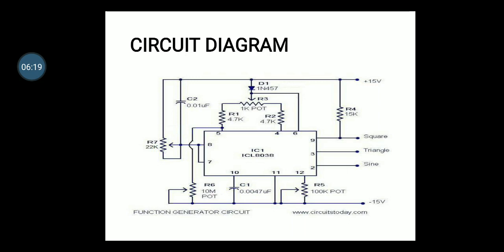Transistors Q1 and Q2 form programmable current sources whose magnitudes are set by external resistors RA and RB. These current sources are driven by an emitter follower, which also compensates the base-emitter voltage drop of Q1 and Q2 to ensure the voltage across RA and the voltage across RB are equal to the input voltage.